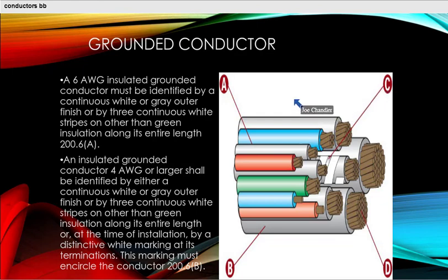Okay, we talked about current carrying conductors, and a grounded conductor is another name for what we often slang term just the neutral. But this is a current carrying conductor also. A neutral sometimes is, but a grounded conductor is always considered a current carrying conductor. Whenever we say we have a neutral, maybe it is, maybe it isn't. It all depends on the conditions.